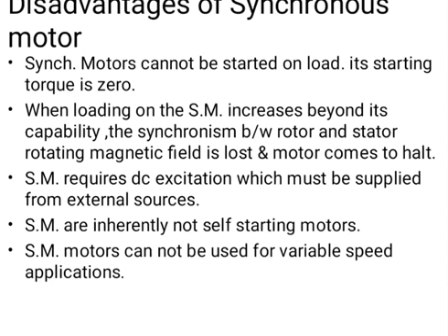Next, the synchronous motor requires DC excitation which must be supplied from an external source, and synchronous motors are inherently not self-starting. And last, synchronous motors cannot be used for variable speed applications. So these are some disadvantages of the synchronous motor.